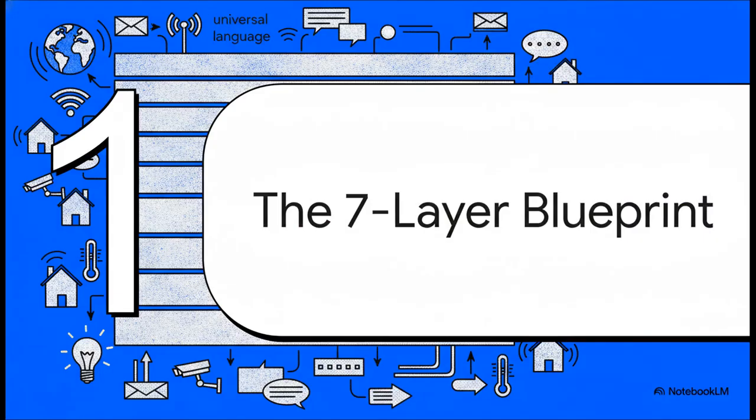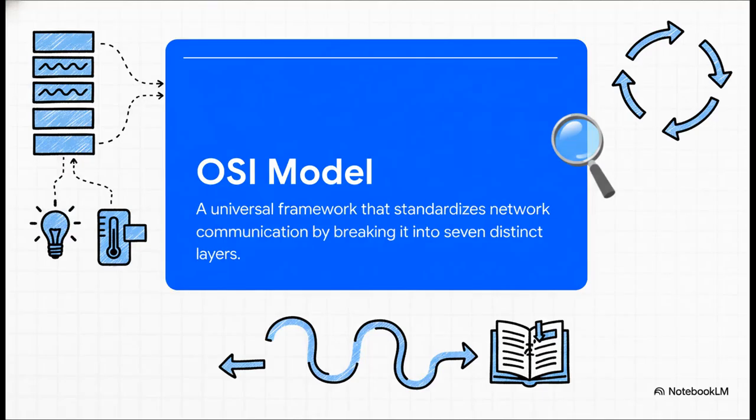So, how do you even begin to build a universal language for technology? Well, you don't start from scratch. You start with the proven, internationally recognized blueprint for communication. KNX is really cleverly built on something called the OSI model. Now, you can just think of this as the universal rulebook for how networks are supposed to communicate. By adopting this structure, KNX makes sure that everything is logical, super robust, and really organized.